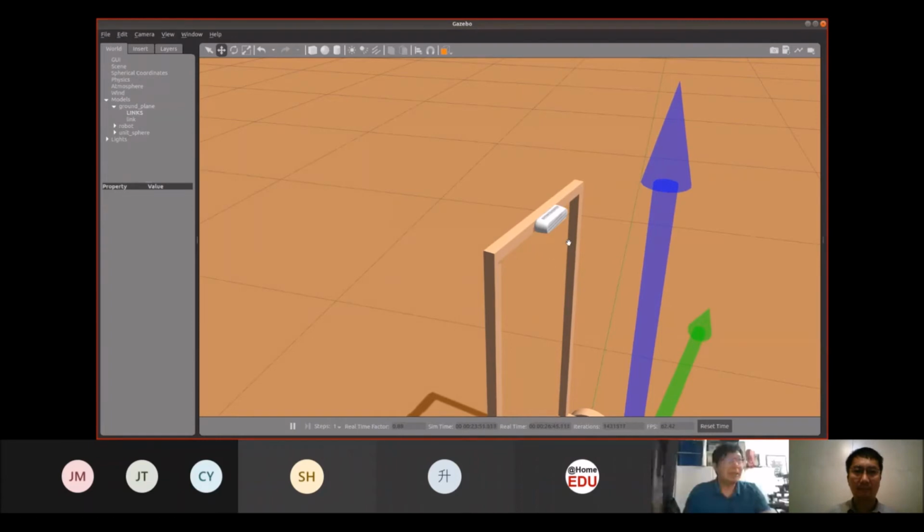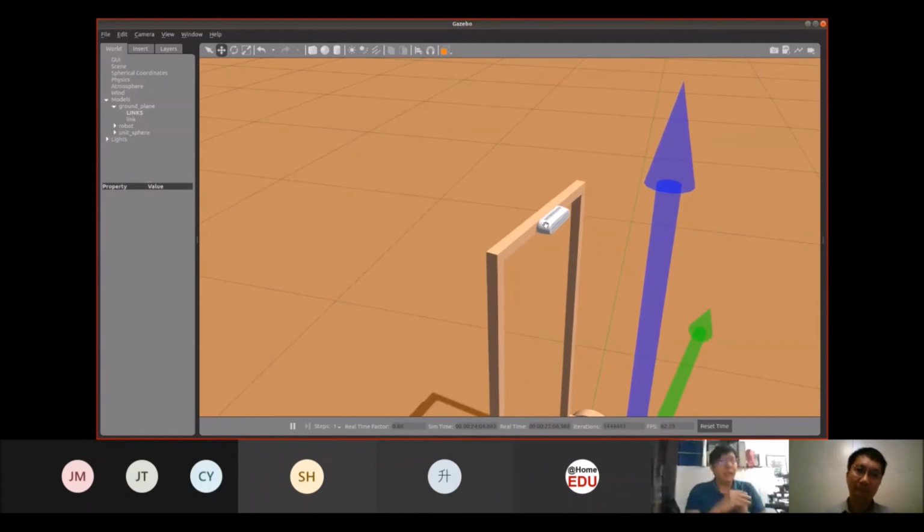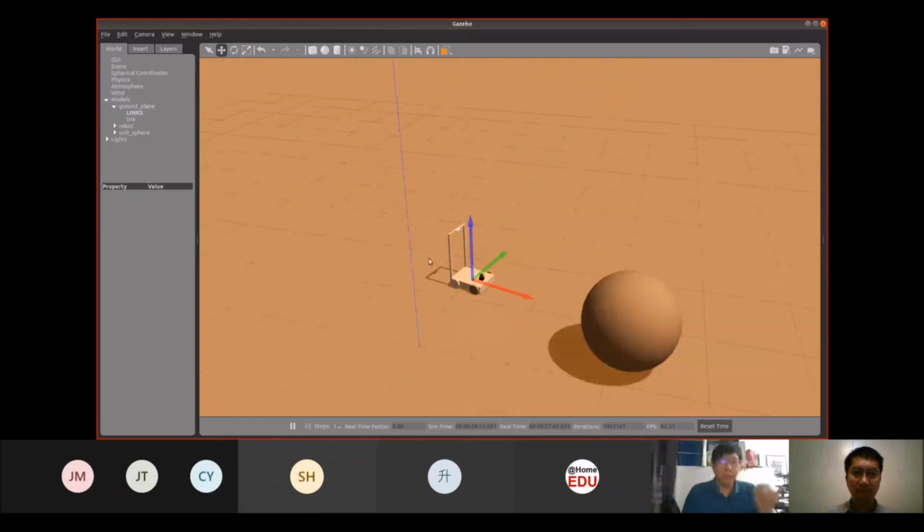So when you're working with navigation and things like that, this white part would not register as a collision point. One thing about URDF is, if you're familiar with SDF, the collision is written in a similar manner, so whatever you see over there can be applied over here also.